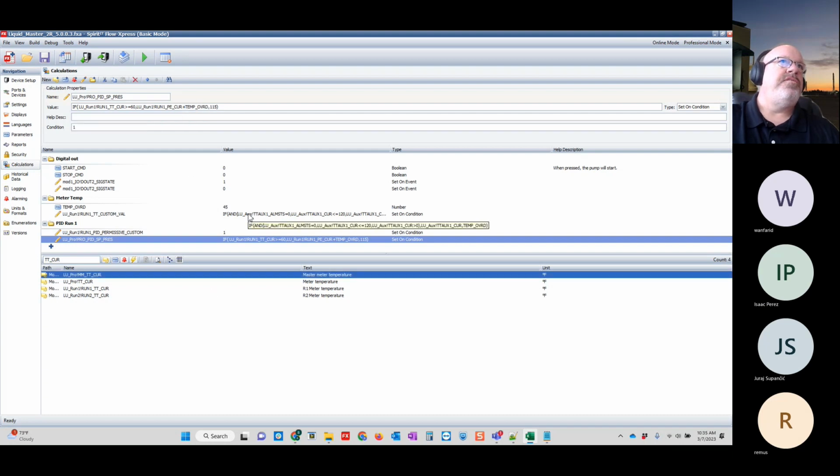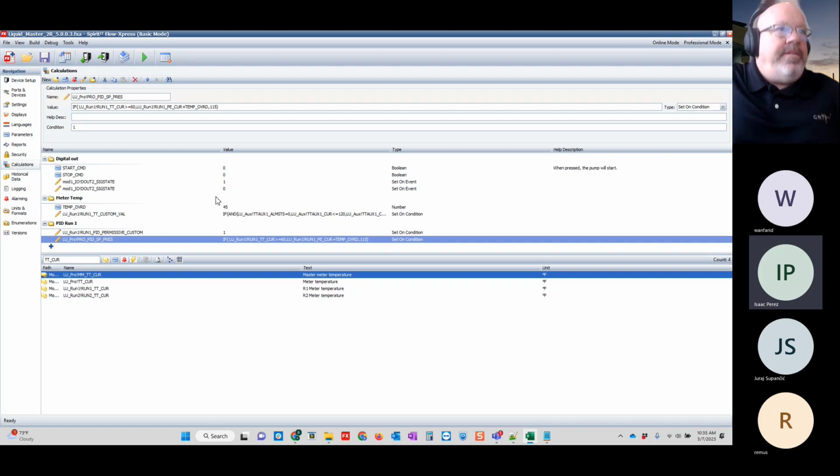All of these calculations, I typically use the debug offline mode to check them, because when I do the debug offline, it also has a little pop-up function called calculation, and it will show you all your calculations and what the results of those calculations were. But if you happen to type something incorrectly right there on the value line, when you hit enter, it checks it as well, right?